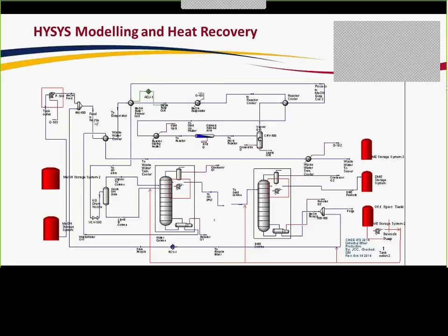So what's happening now is the methanol is going to come through a couple of heat exchangers, and it will be vaporized in this process as it makes its way into the reactor. So at the reactor, it's almost 100% methanol, it's 350 degrees Celsius, and it's a pure vapor.